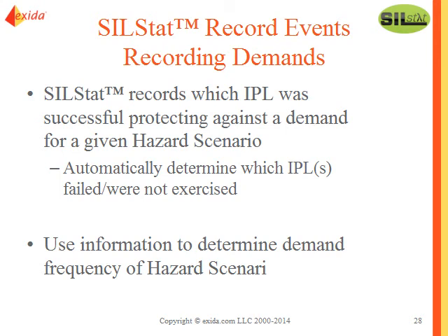The standard focuses on safety instrumented functions. It tends to not focus at all on any other protection layers, but reality says, I may have a SIL 1 safety function, but I took 2 orders of magnitude credit for my relief device. So you kind of want to keep track of this, so we can use this information later to determine the actual frequency of the hazard scenario.